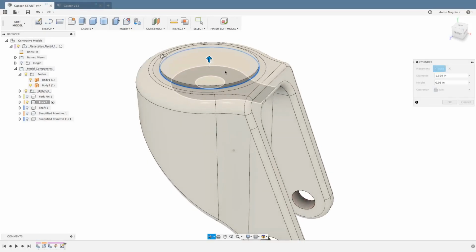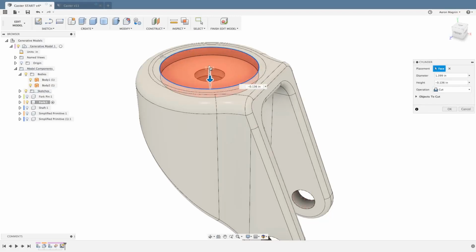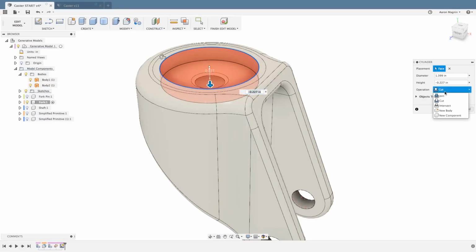All I want to do here is slide the cylinder into this body a certain amount. I want to make sure there's actually the pin that goes through the top there. It's, I think, press fit or something. We want to make sure to get enough of that material so that we have an area for that press fit operation as well. So we'll drag this down a certain amount, and obviously I don't want to do a cut. I want to use a different type of operation here.